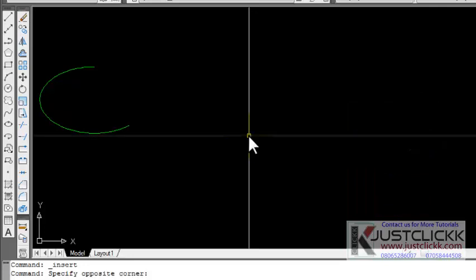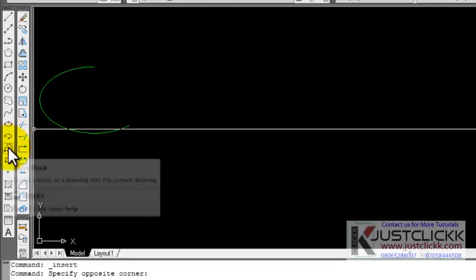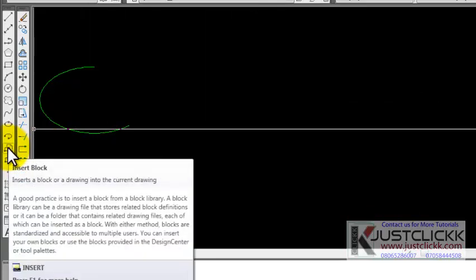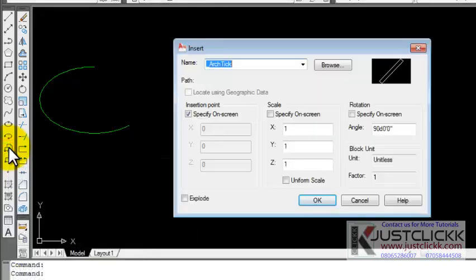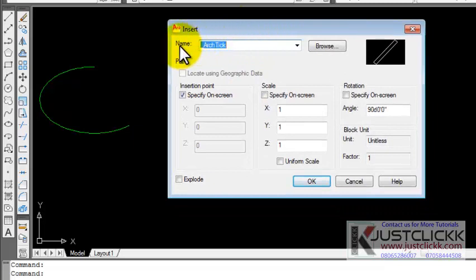Now, inserting blocks. Inserting a block in AutoCAD is something you do by clicking on the tool there, and it takes you to a dialog box like this. If you have already created some block objects, for example your windows, doors, and door panels or whatever, they will definitely be on this list here, but because you have done nothing, you won't see them.